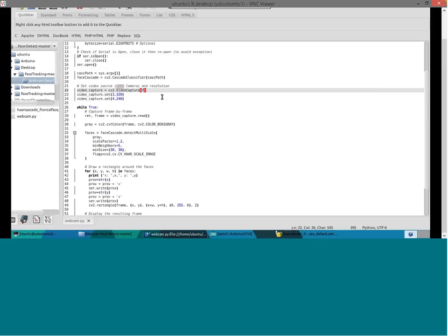Now, since OpenCV is quite a power-demanding application, we do not use a full HD or high resolution. We strip it down to 340 by 240 in order to obtain an optimal balance between resolution and computational speed, of course.